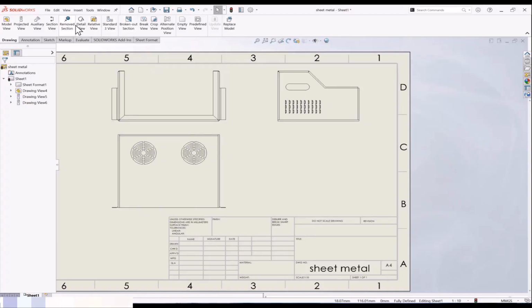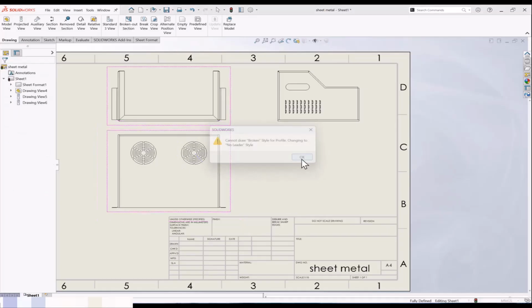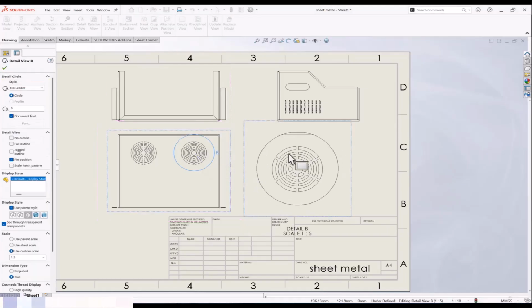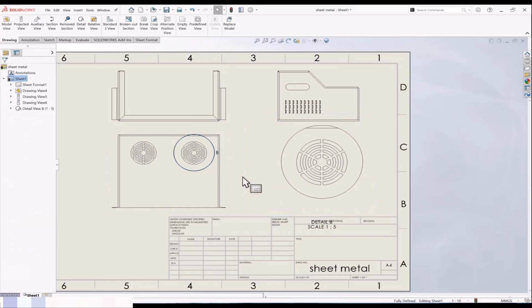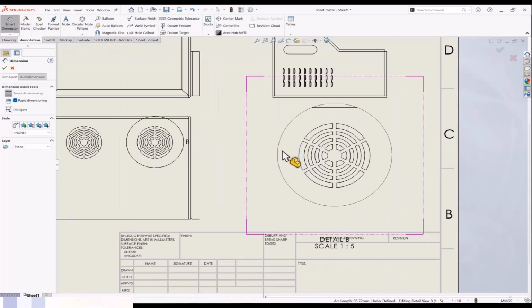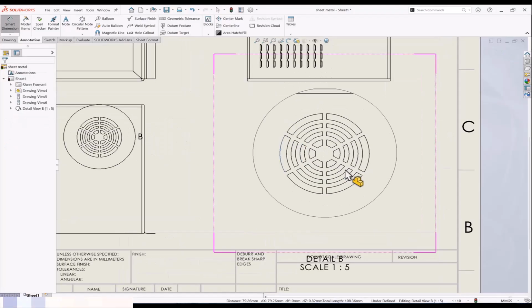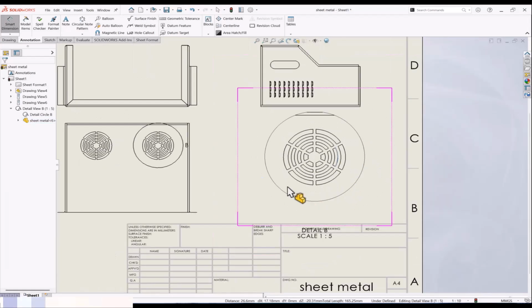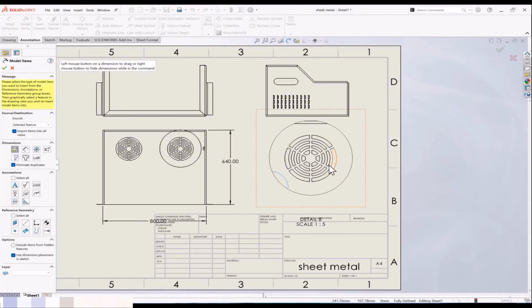Okay, let's cancel. Let me take it again. So by default that is on 1:5. So you can see here, it will become 1:5 scale. But when you do dimensions, they will remain at the same scale. Dimension scale will not change. Dimension scale will remain the same. If I'm measuring any of the dimensions, for example, so here, if we can see some values. This portion, I think we cannot have, but let me try with a model